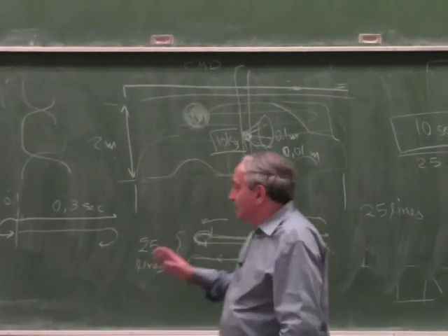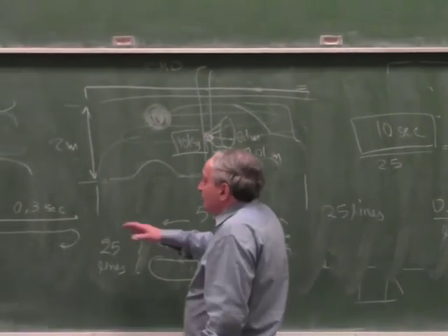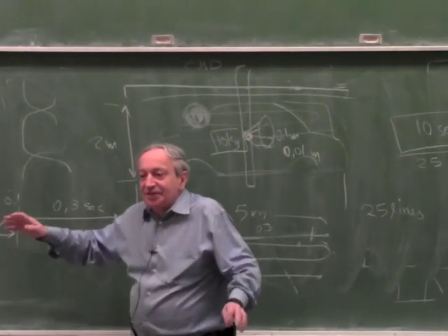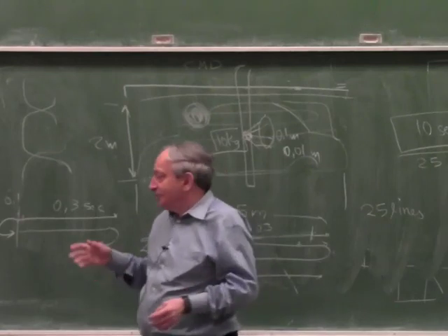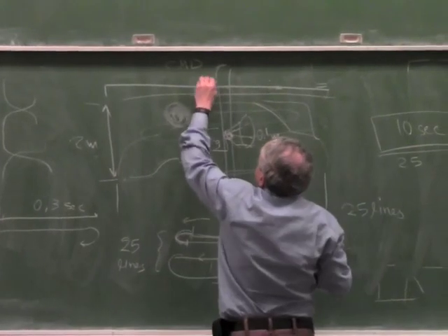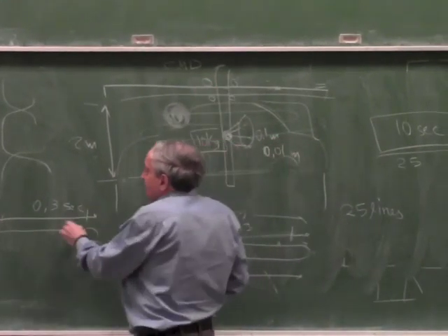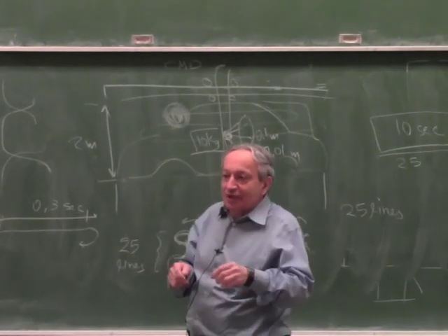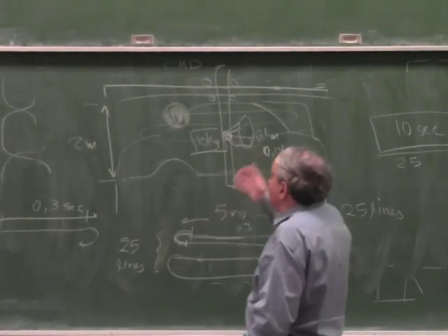Okay, so is this clear so far? Good. So during the linear travel, if it's constant velocity, in theory there is no power needed, it's just to overcome friction. But if it runs on some nice rollers, it slides. So this part is of no interest. It's just of interest if I use a motor, I have to check what speed the motor has to run, because at the end I have to suggest an actuator.